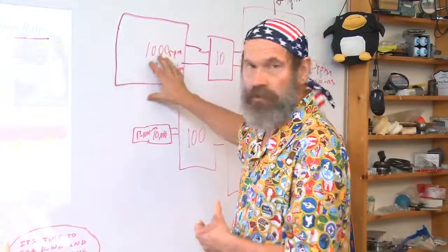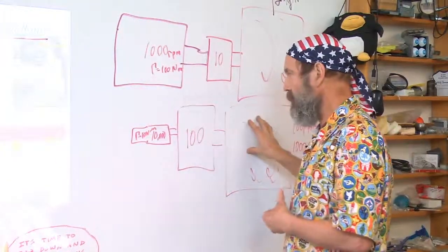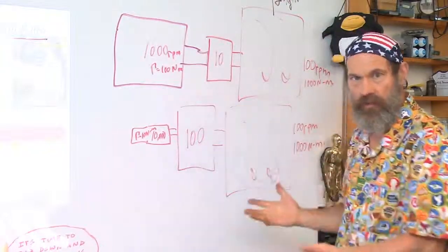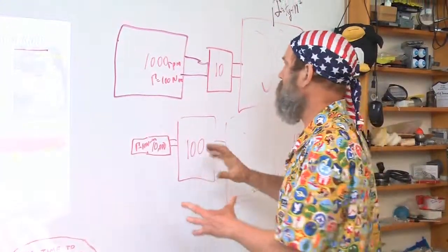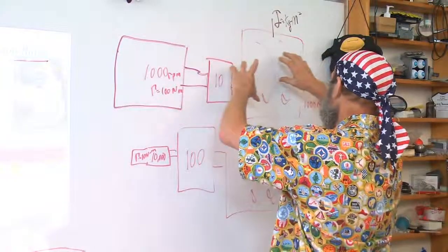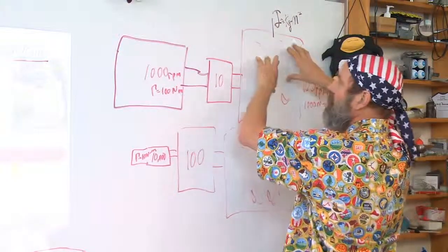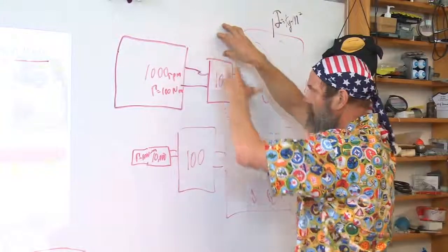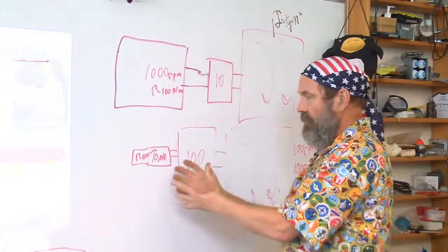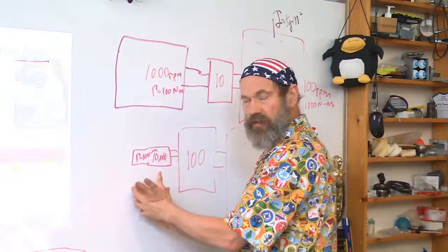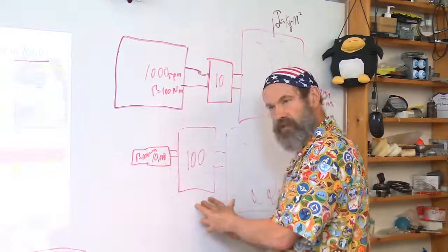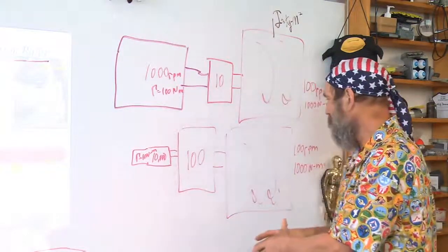So when you go to pick the motor and the load and the gearbox, they all have to work in harmony. You can start by picking a motor. Well, you have your load and see what transmission ratio that gives you. And then you can go to the other extreme, the higher end of speed of the motor, lower torque. What transmission ratio is required then to drive your load?